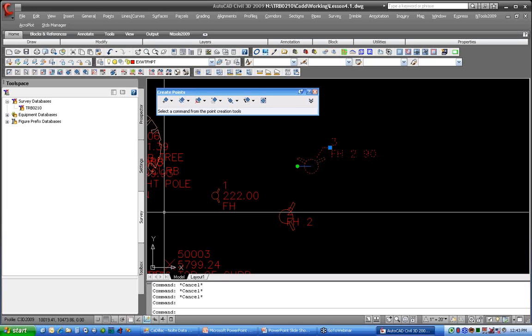That's kind of critical for the surveyors because my intent is at the end of the month to disable 2007, meaning that this is going to be the only place you'll be able to find Trimble link to download a data collector and create a fieldbook file. Once you've done that, you are more than welcome to go back to your LDT 2009 and go to the survey menu there and import your fieldbook file and work in Land Desktop. But I thought it'd be nice to at least have an understanding of points, description keys, so that if you did import directly into Civil 3D, you'd at least be able to manipulate and work with your data.